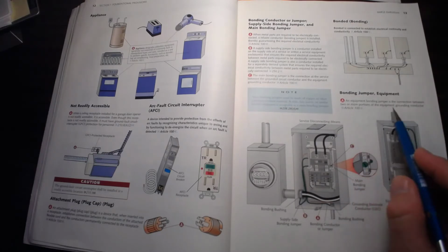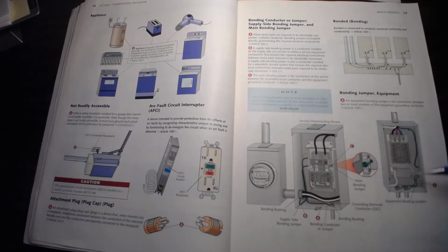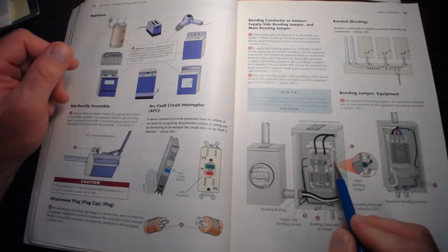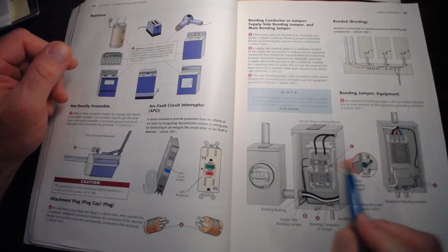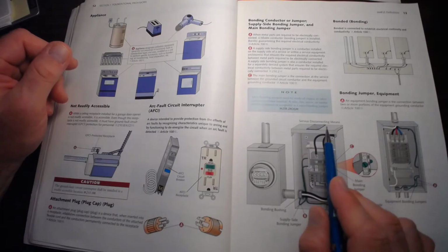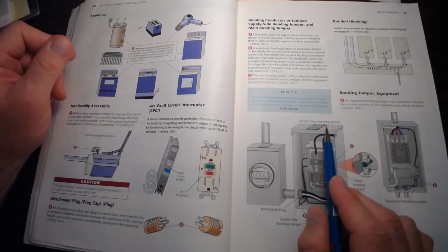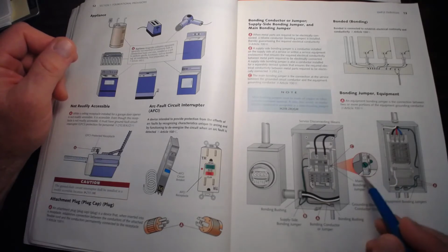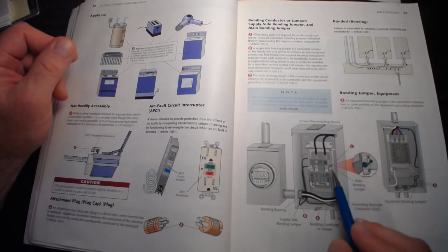Now, an equipment bonding jumper is the connection between two or more points of the equipment grounding conductor. So the bonding jumper could be a screw. If you've ever seen a green screw in a subpanel, that green screw would be screwed through the neutral bar to the back of the can, and that would bond it, and that would only be done at the service disconnect or the first panel off of a separately derived system. So if this was a sub panel, you take that screw and you throw it away, because you do not want to put that screw into a sub panel.